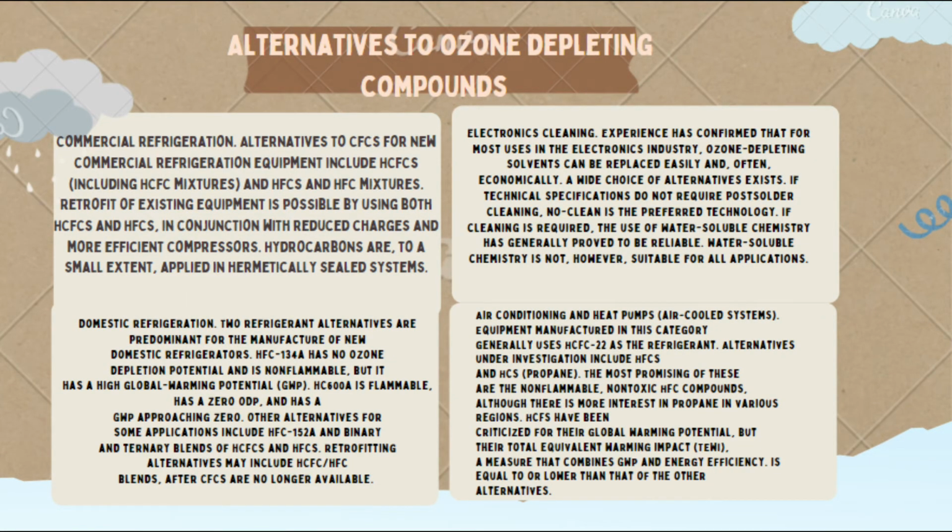Alternatives to ozone depleting compounds. Commercial refrigeration: alternatives to CFCs for new commercial refrigeration equipment include HCFCs. Retrofit of existing equipment is possible by using both HCFCs and HFCs. In conjunction with reduced charges and more efficient compressors, hydrocarbons are, to a small extent, applied in hermetically sealed systems.